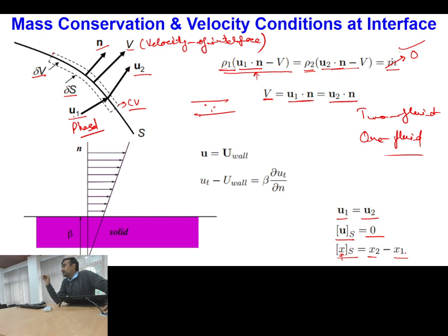So it means at the interface, considering that the interface is sharp, we will have the no slip condition, which clearly defines that at the interface we have a high amount of shear stress, which forces the molecules to have the same velocities. Now, in certain cases, if we have boiling, condensation, etc., or when we are looking into the interfaces at the molecular level, then we may have some partial slip between the two velocity values.